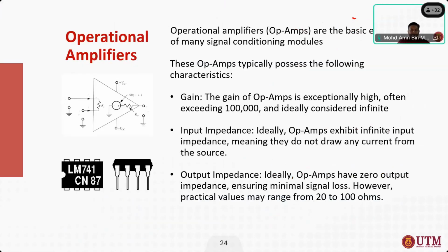Okay, some characteristics of the op-amp. The op-amp has high impedance input and low impedance output. What it means by high impedance input is that I plus is 0 ampere, and the input impedance Z will be equal to infinity ohm. We'll see that in some examples.